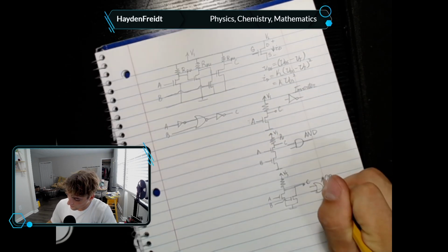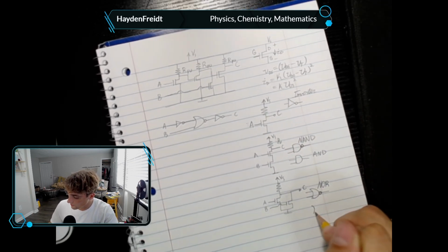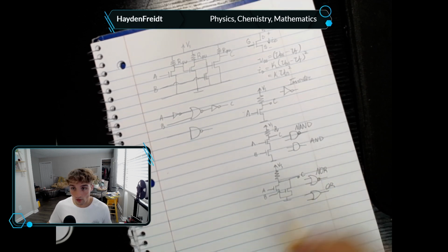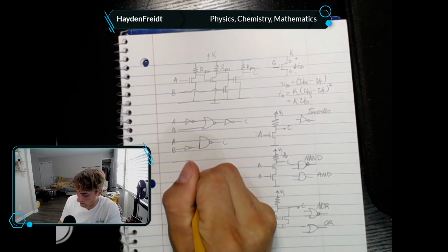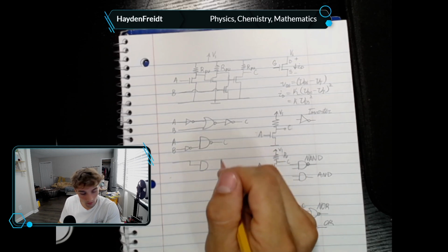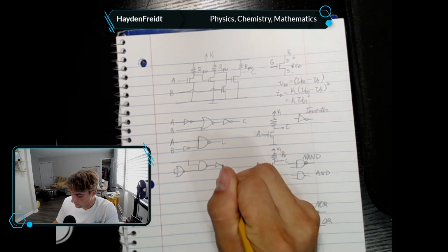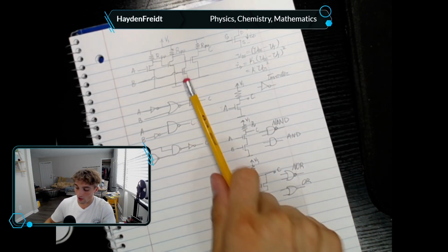VS. All right, this with the N in front would therefore be a NAND gate. That's an AND gate. So there's a distinction between this very minute notation. You have to look at these distinctions in the drawing, and that determines the function of the logic abstraction. Another way of doing it is like this. And that's C, A, B. So these are 3 different ways that we can draw this logic diagram.